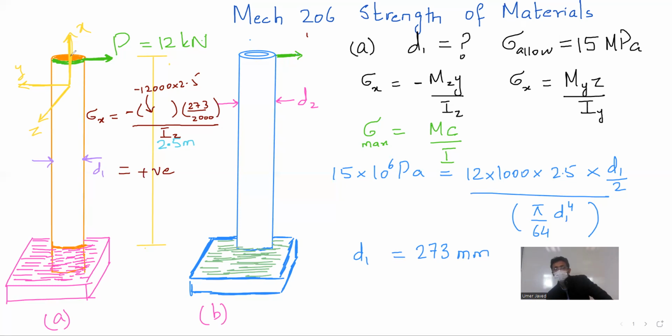When y is 0, you are talking about right at the centroid. The bending stress at the center is 0 because the y distance from the neutral fiber is 0. y at this point will have an intermediate value, somewhere between the maximum and the minimum. But y maximum distance from the neutral fiber will give you the maximum bending stress and subsequently the maximum strain.